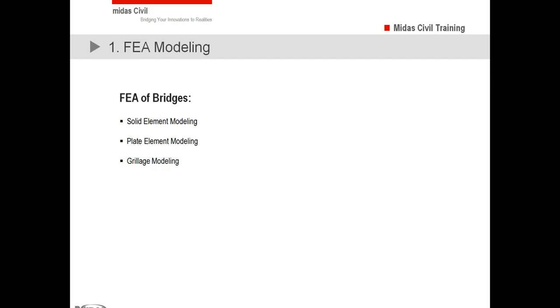They are 3D finite element analysis solid elements. You can also represent the entire bridge using shell elements, and the grillage modeling approach can also be done. So these are 3 different types of modeling approaches that can be applied in any finite element analysis software, including Midas Civil, and the practicality increases as you go from top to down, and accuracy increases as you go from